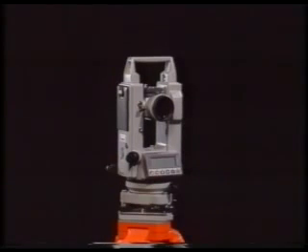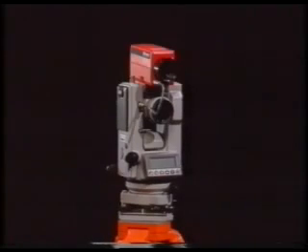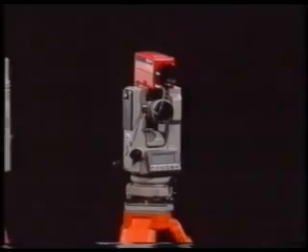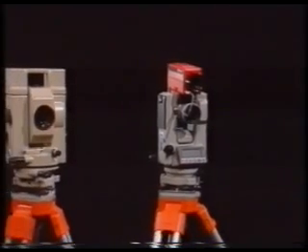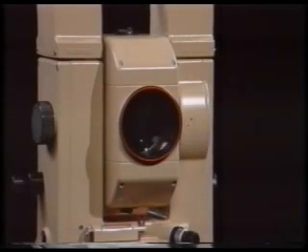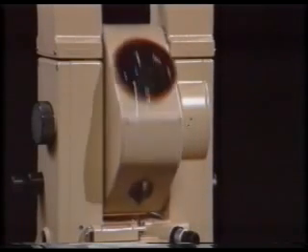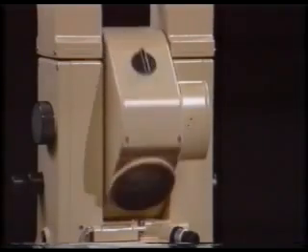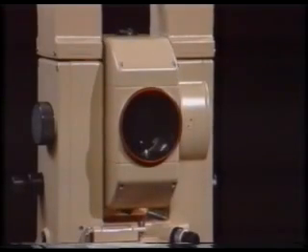EDM infrared instruments are invariably used in conjunction with theodolites, and they can be combined in one of 2 ways. Either the EDM instrument comes in the form of a separate add-on unit, which fits onto a special bracket mounted either on the theodolite or on the telescope as shown here, or the EDM instrument and the theodolite are permanently combined into one complete system. Both types of configuration provide complete angle and distance measuring systems in one unit, and for that reason are sometimes called total stations or electronic tachyometers.